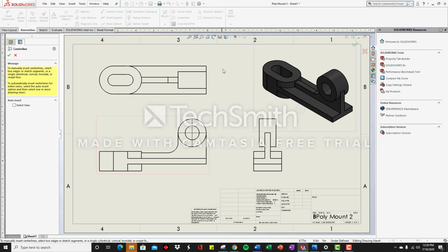So we're going to click center line, and we're going to put a center line through this part. You're going to click this line, and you have your center line made. We're going to do a center line from here to here. So you click this line and click this line. We're going to do a center line with this rib here. There and there. Just as a point of reference when we put our dimensions. And we're going to do a center line here and here, here, and here. Okay, green check mark right up here.